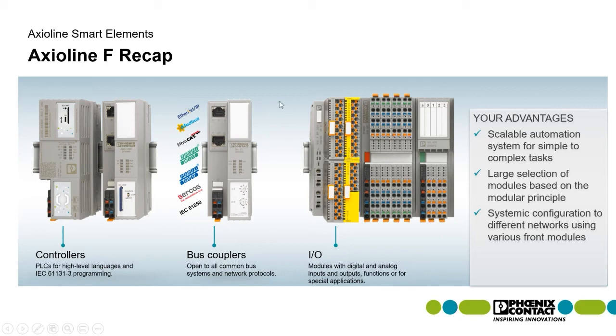If you put this controller on the front of this, you're now taking this I/O station and turning it into a PLC. Because a PLC is just a brain with I/O. With an interface module, it's just a kind of a dumb interface. So we can turn this Axioline product portfolio into a full control offering. So if we can replace the PLC, we can replace the I/O, and we can replace your network all with an Axioline solution and reduce the space dramatically in the system while giving you the flexibility Ethernet gives you to distribute this throughout the field.